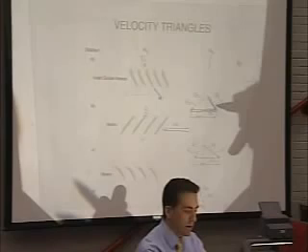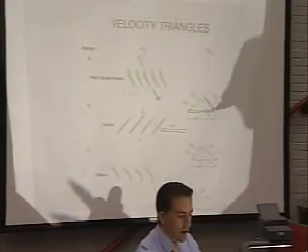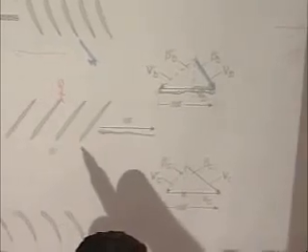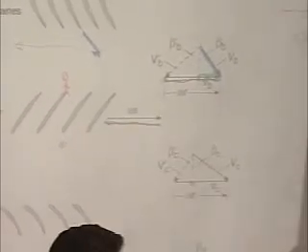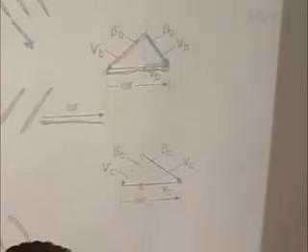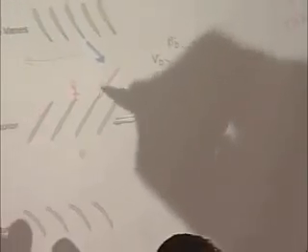So if I add the stationary frame flow vector to the omega r that gets me to the rotating frame, I then end up with, I'll try and be consistent here, the relative frame velocity, which you can see lines up nicely with these blades.